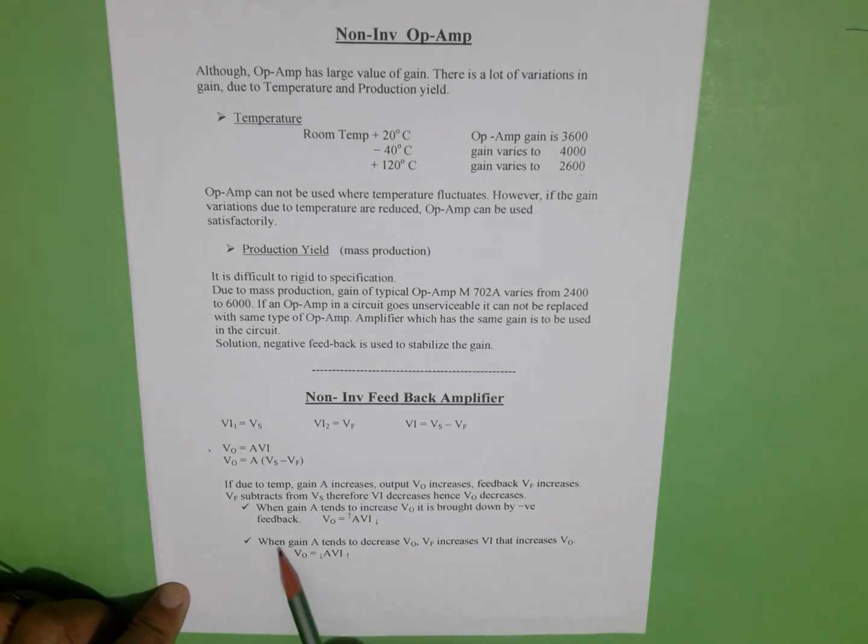And when gain A tends to decrease, now gain A is decreasing due to temperature, it is going to decrease V0. Vf across R2 decreases, V input increases, that increases V naught.